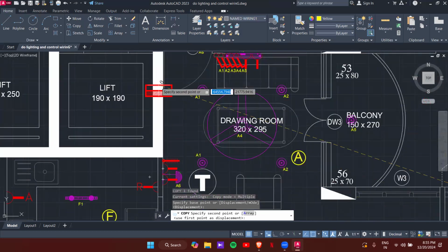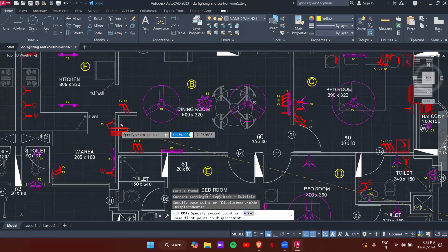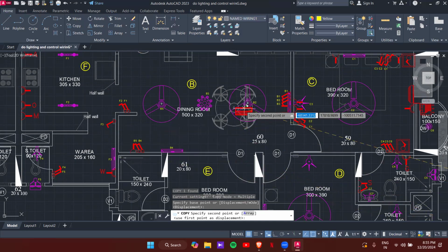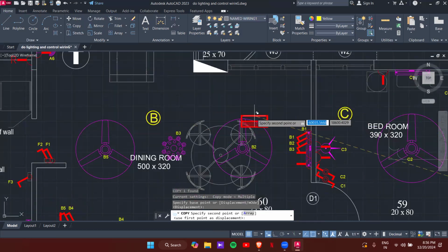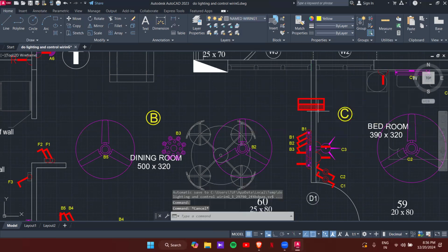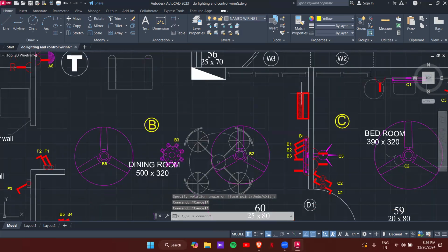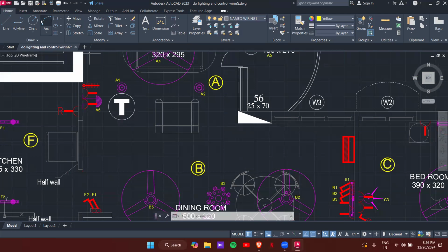So no chance here. And again, this one is a hatched portion. Okay, and here also we can place, but I will prefer somewhere not noticeable. Okay, so I will go for this side or this side. So both space you can take. For now, I will place it out here. Again, this is a dining room, still a common area. Everyone should have common access for the DB. Okay, so I will place it here. Then I will rotate this one. Okay, that's it. Now from here we can start the connections. Okay, so conduits normally will be represented by a polyline.